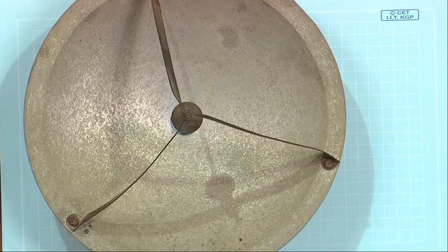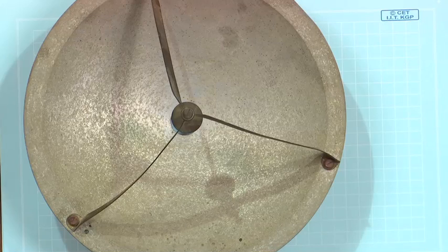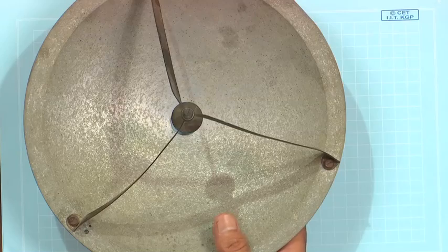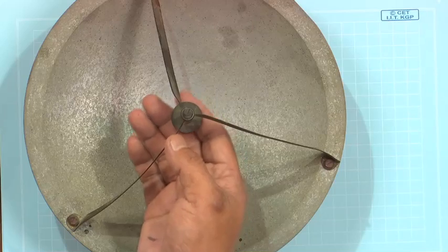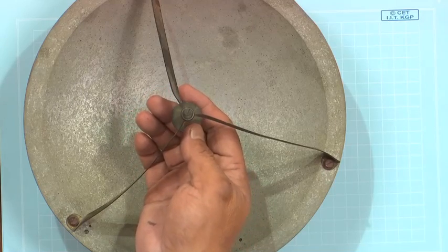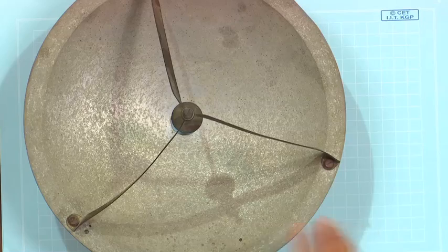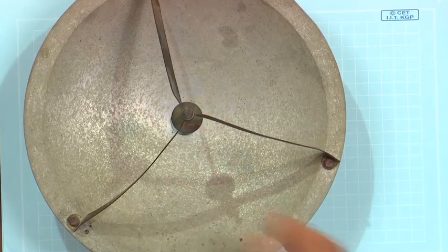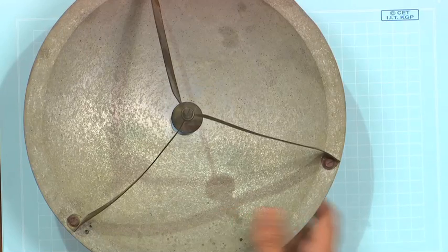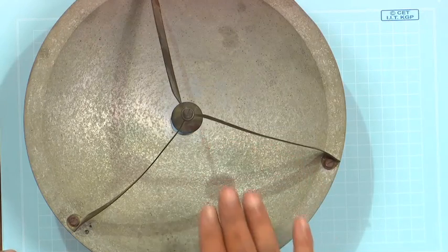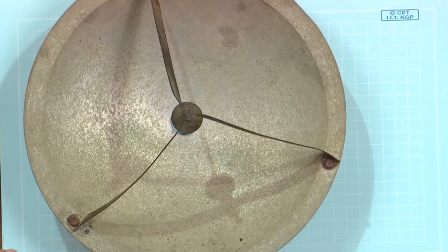Actually, their signal will be so low, it is almost a noise. If this thermal noise comes, then they will not be able to detect it. So, that is why they do not go for this single feed system. Various choices are there, single feed and single reflector, etc. So, their choice is the dual reflector antenna system. This type of feed, which is the classical feed, is called prime feed or front fed feed. So, the feed is in front of the reflector.